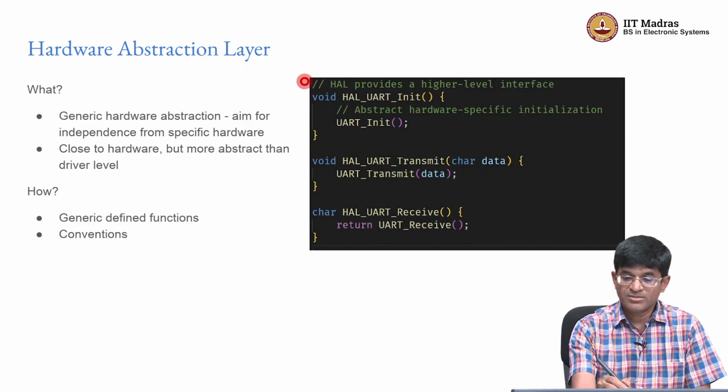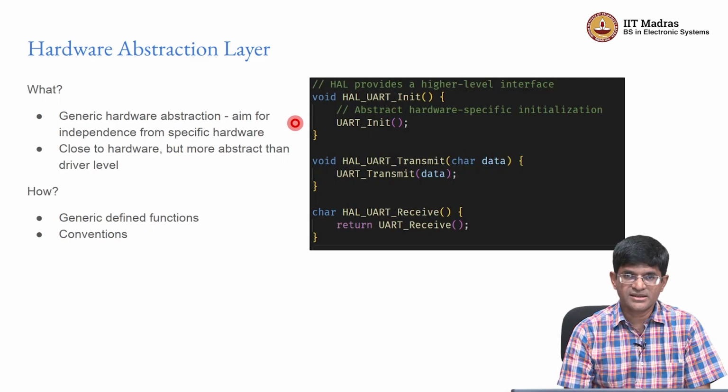Right? At this point, as you can see, we are two steps removed from the actual hardware. We don't need to worry about the direct registers, but we are in turn calling functions whose job is to know which registers need to be manipulated in which way. So the HAL, or the hardware abstraction layer, can be made sufficiently generic that it covers multiple different systems. Right? It is easier, at least. It's basically providing more abstraction for you to do so.